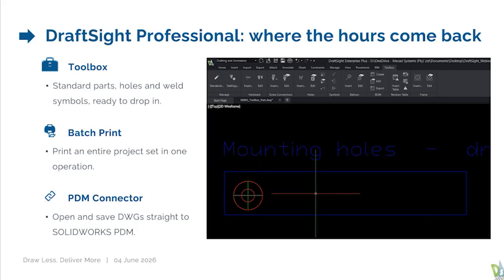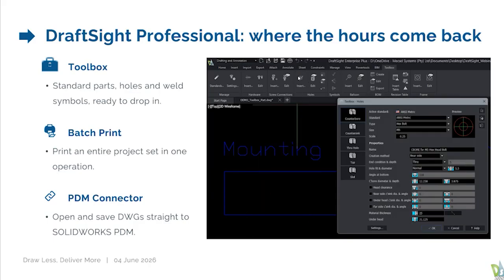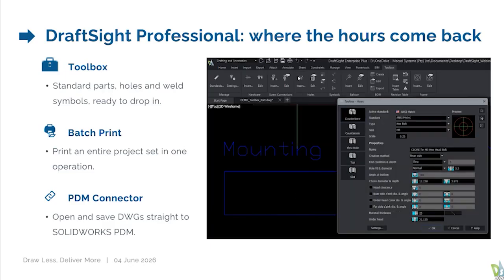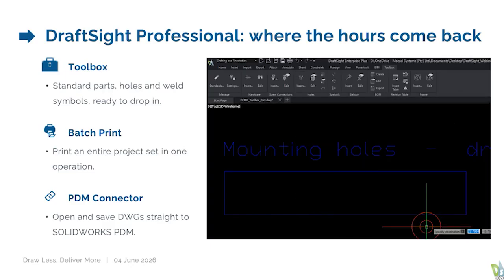The nice thing about this as well is it has attributes assigned to it. So when you do your labels or you're adding your notes, you can then just pull it from the hardware itself, because its attribute is already applied to that sketch. So that saves a designer from drafting 2 circles, 2 lines, and also adding notes.